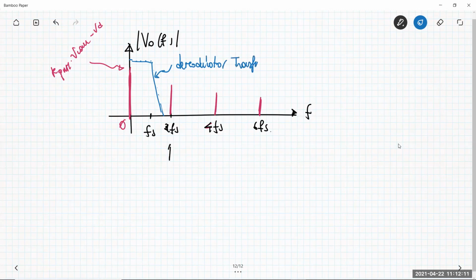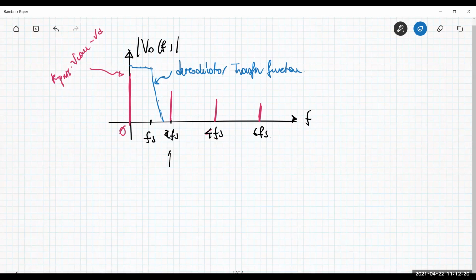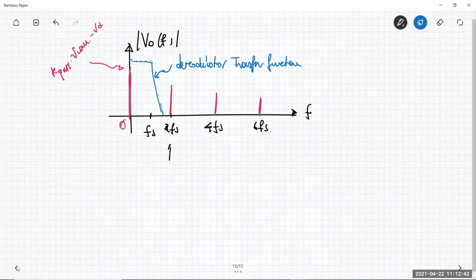Transfer function. So this also means that I'm expecting from this solution an amplitude of the peak-to-peak ripple of the output current I naught which can be reduced, okay? Because now the filtering action, having the same filter, is more effective than the same filter applied to a waveform that has a frequency of fs, okay? So this can be, for sure, an advantage.